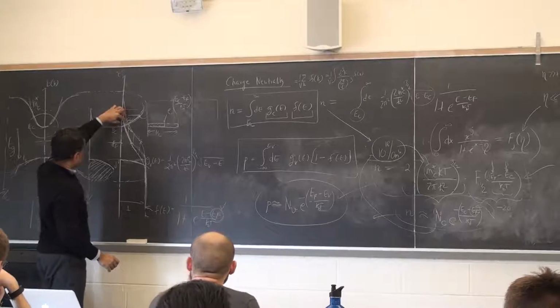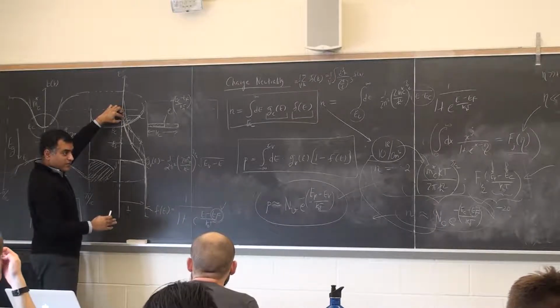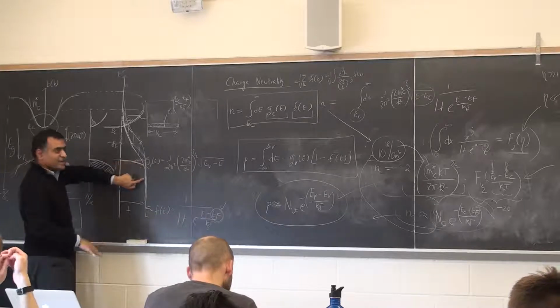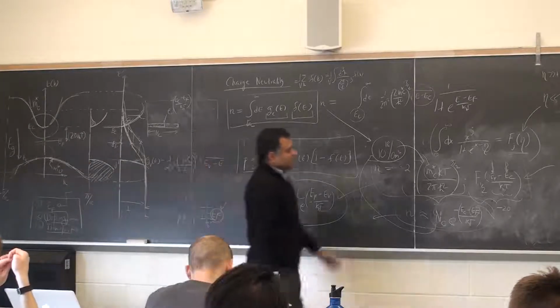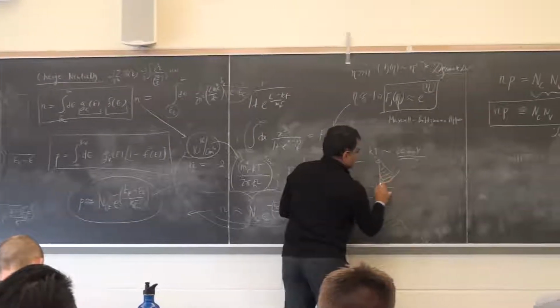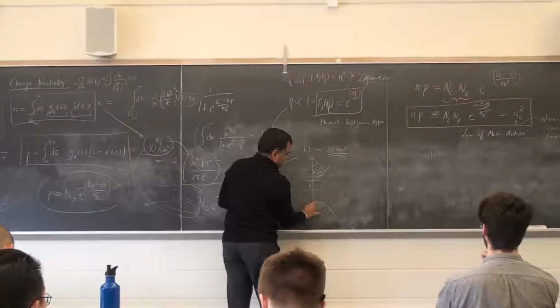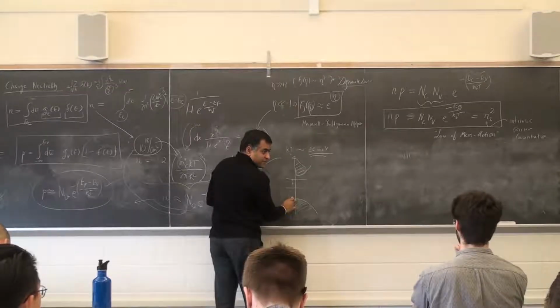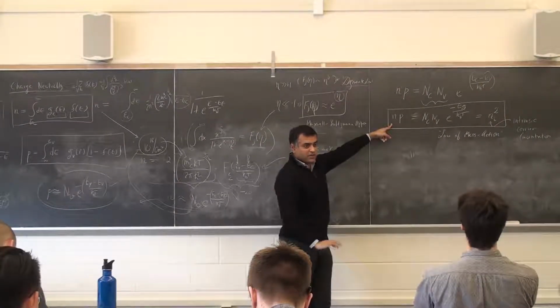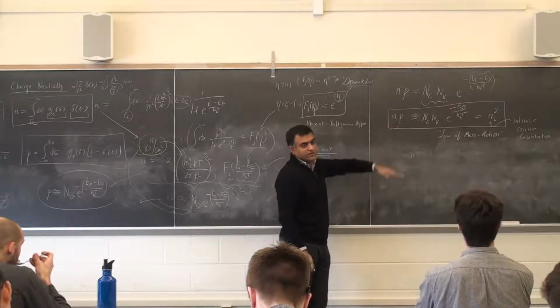Therefore, the occupation function of these things went up, right? Whereas the unoccupation, or 1 minus this, went down. So as a result, it will increase my electron concentration, exaggerating a little bit, and it will decrease my hole concentration. Right? And in what ratio? It's always going to be in this way. N times P is always constant. Right? So if I move my Fermi level.